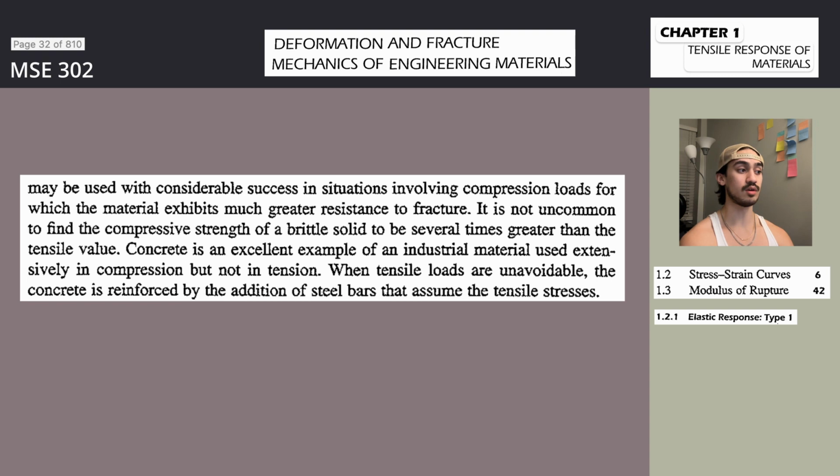Should an engineering design require a material that allows only for elastic response with large energy absorption, such as in the case of a mechanical spring, the appropriate material to choose would be one possessing a very high yield strength with low modulus of elasticity.